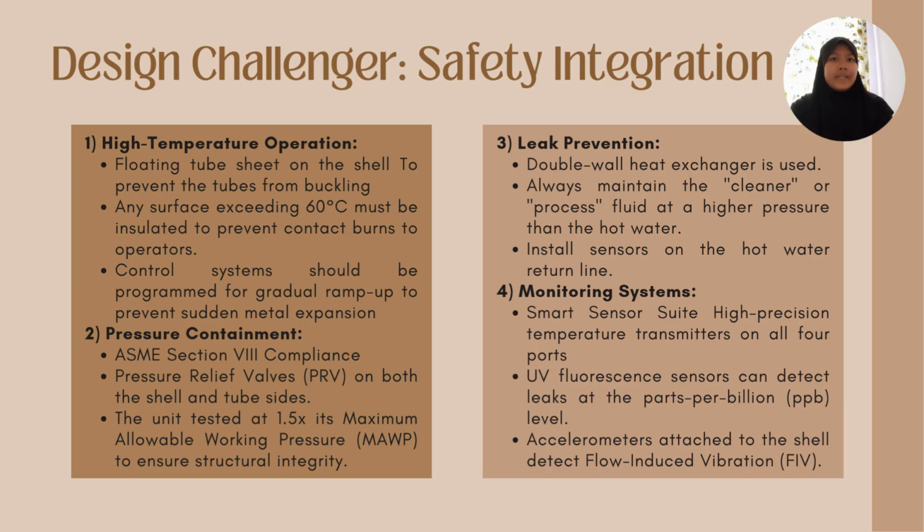Safety is our final pillar. Our design includes pressure containment compliance with ASME Section 8 and pressure relief valves on both sides. Second, leak prevention, the use of a double wall heat exchanger and keeping the process fluid at a higher pressure than the water. Lastly is smart monitoring, high precision temperature transmitters and accelerometers to detect flow-induced vibration before they cause failure. In conclusion, this design safely and efficiently meets all process requirements for the hydrocarbon mixture.